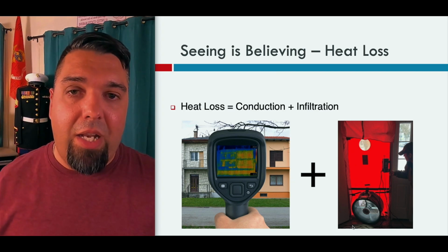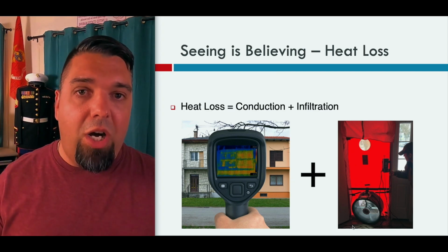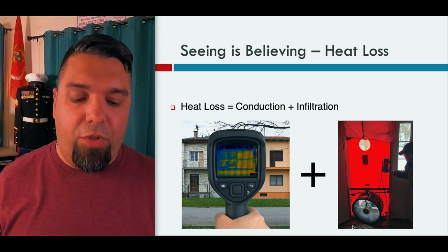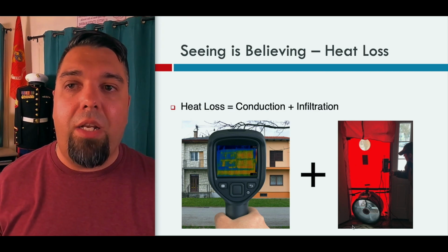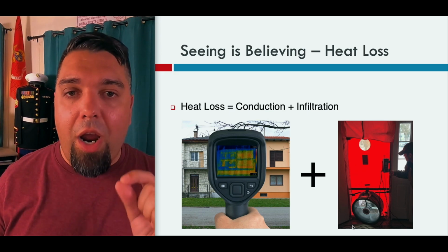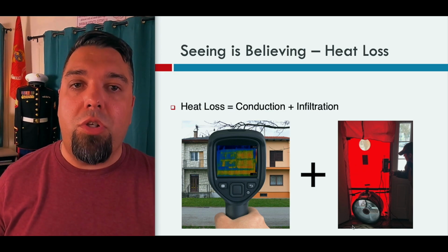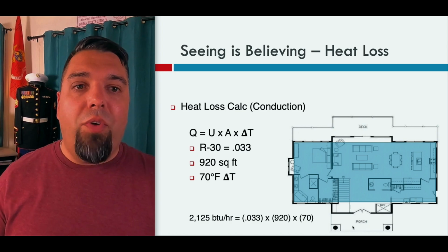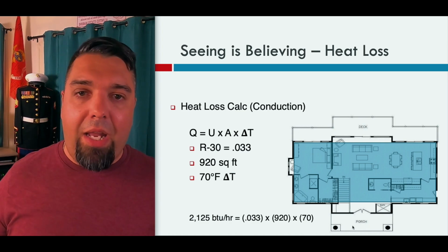I won't get into that today. Just keep in mind, heat loss total is conduction plus infiltration. So we're going to talk about the conduction side and what the weighted R values actually do to your heat loss, all right? So let's take this example of I poked my head in the attic.